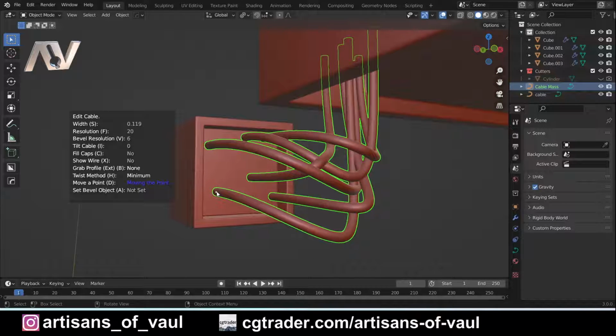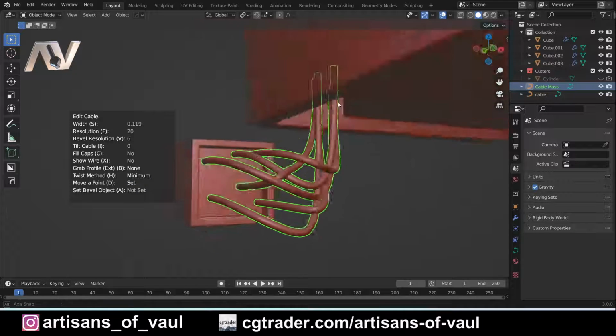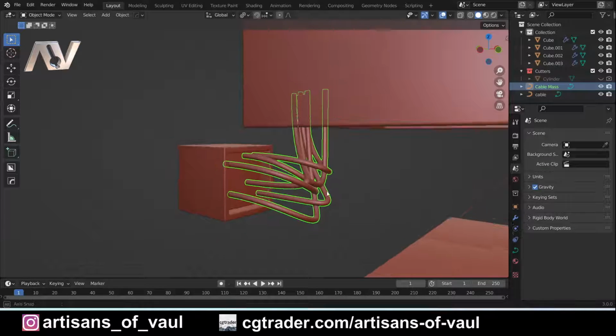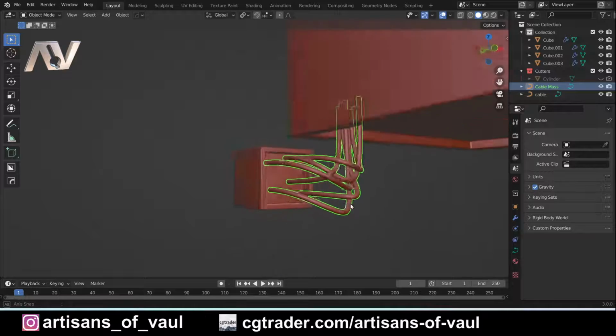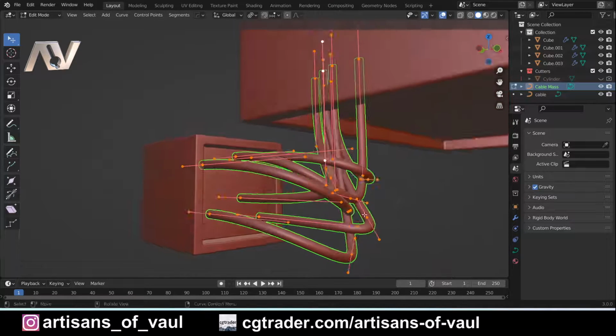I can go D to there, so I can do it the same over here as well, D on that one, okay? It just goes to whatever the closest cable is, and I think that's fantastic. So click off. I've got this already made. I've just made a load of cables in no time, and if I really do want to, edit mode, I can start editing these cables.